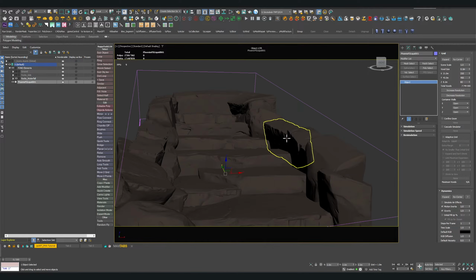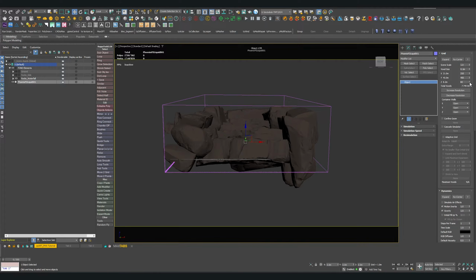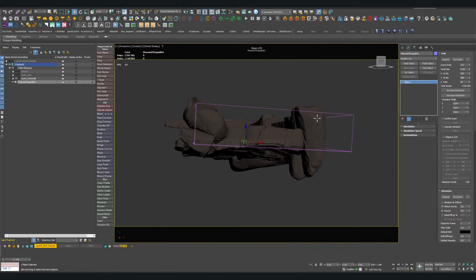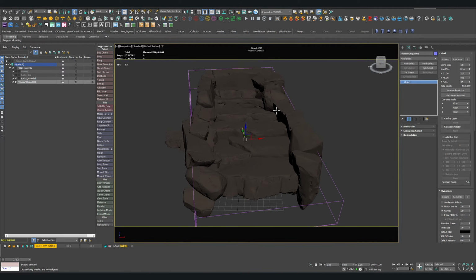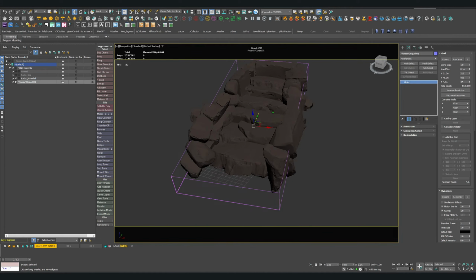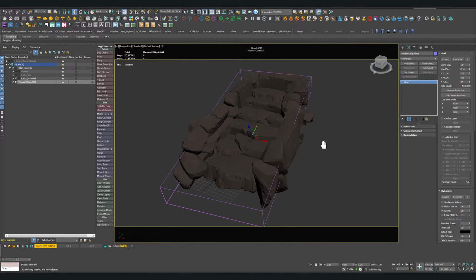Now it is too high. We don't need this height right here. So we bring that down a little bit. So about there, this should actually do the job. It's not going over that edge anyways. And now we can take a closer look at its setup. So right now we have 4.5 million particles. This is usually not enough for such a simulation.